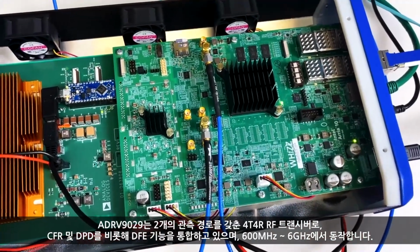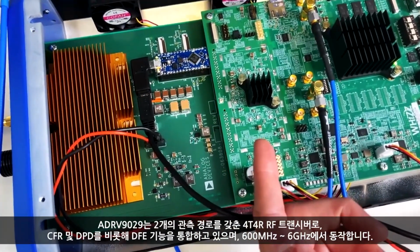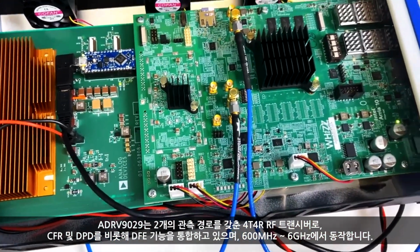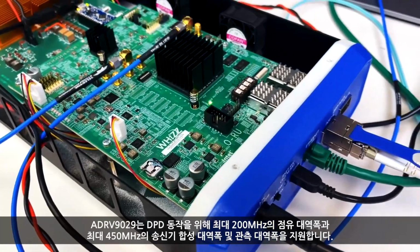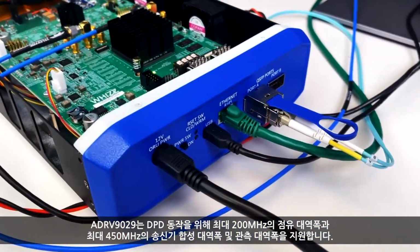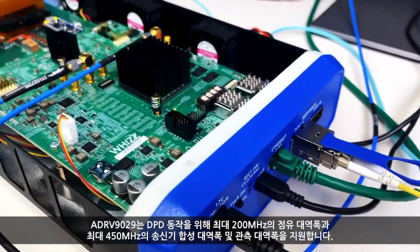The ADRV9029 is a 4T4R RF transceiver with two observation paths and integrated DFE functions including CFR and DPD, operating from 600 MHz to 6 GHz. It supports occupied bandwidths up to 200 MHz and transmit synthesis and observation bandwidths up to 450 MHz for DPD operation.